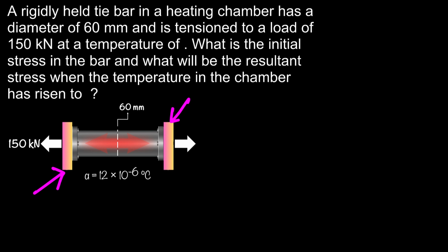Now that is trying to prevent the system from expanding, and as a result it's causing stress to be induced. And what we're going to calculate here is the resultant stress that happens because it's trying to expand but the wall or the rigidly held structure is trying to push back. So let's go ahead and calculate the resultant stress.